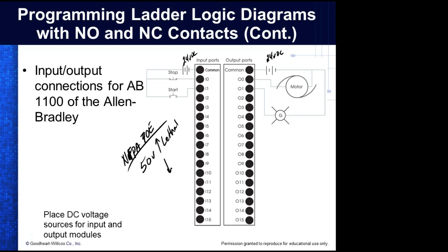What changed is when we started adding all these electronic sensors, these position sensors, optical sensors, and laser sensors. These guys have to work on a DC voltage. So PLCs themselves have established 24 volt DC as the standard DC voltage. Now I can buy sensors that are set up for 24 volts. Does that make sense?